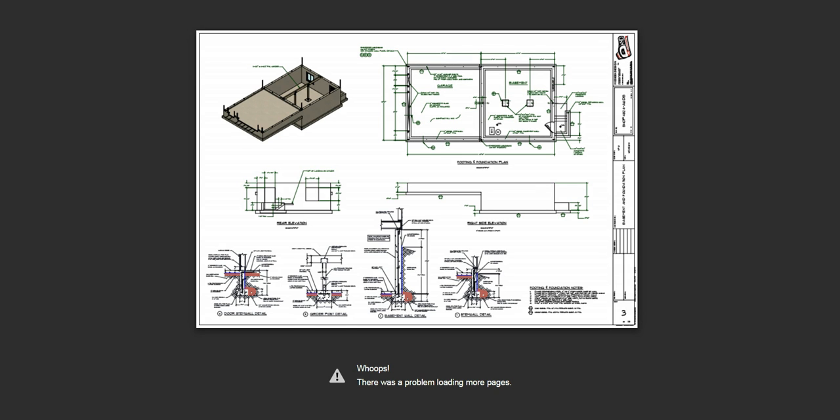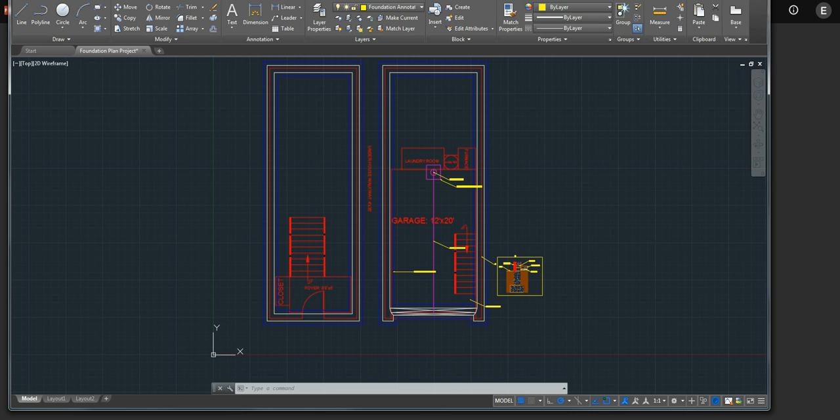This video will demonstrate how to create drawing sheets and views within a drawing sheet using AutoCAD. So far, what you have been doing in AutoCAD has been all your drawing in what's called the model space. This is where you've been making all your two-dimensional or three-dimensional drawings, depending on what level you've gotten to. The way drawings are documented or printed is on drawing sheets.